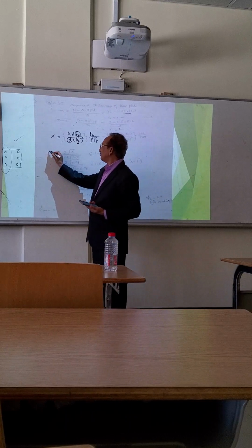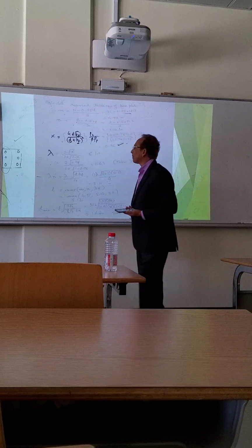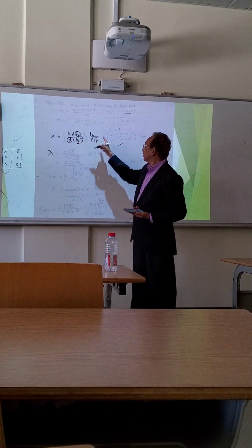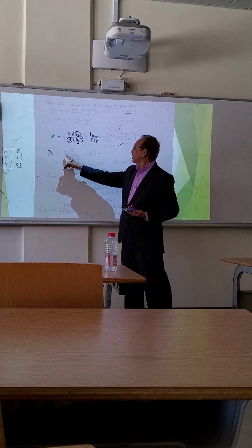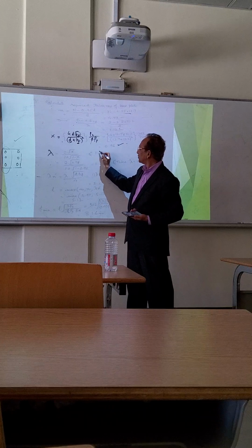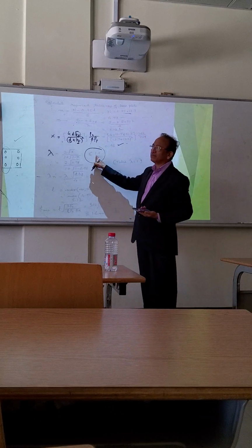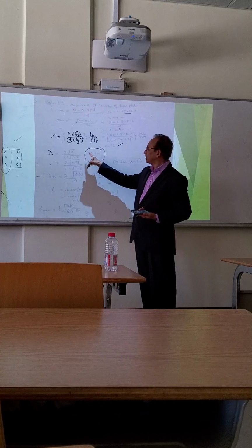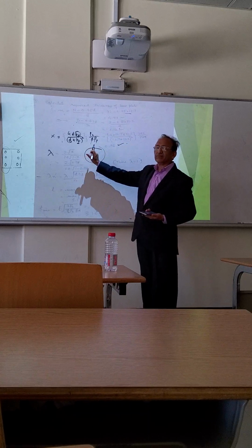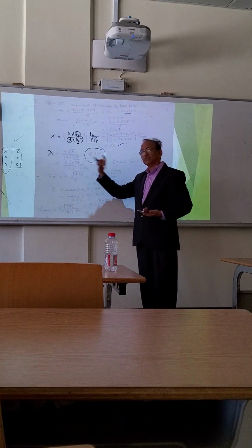Then you can calculate lambda. This will also be in the formula sheet. So 2 into square root of x, x you have calculated by this formula, divided by 1 plus square root of 1 minus x, and this value should not be more than 1, maximum 1. If this value is coming out to be 1.23, 1.4, you will just keep it as 1 maximum. If it is less than 1, keep that value.